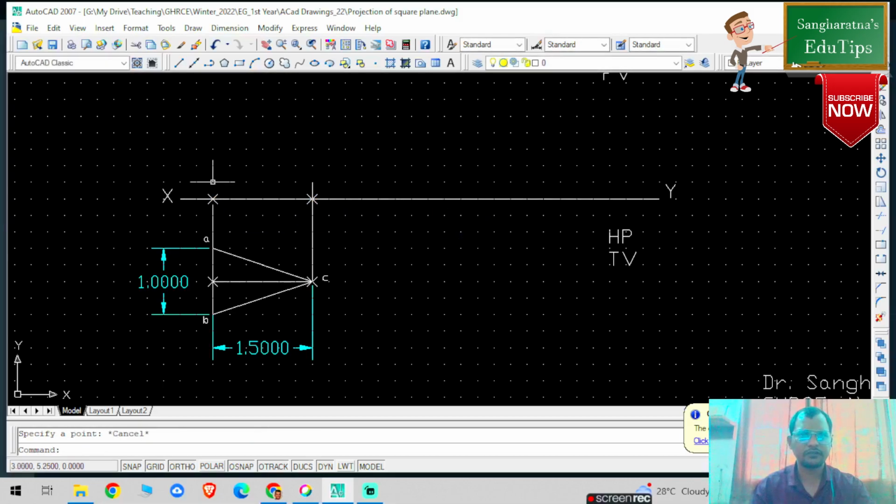Immediately convert this particular projector into cyan, escape. Now give the naming: text, select anything on the screen, point to 1, and rotation angle is 0. So this is my A dash, B dash, and this is my C dash, and this is basically my true length.